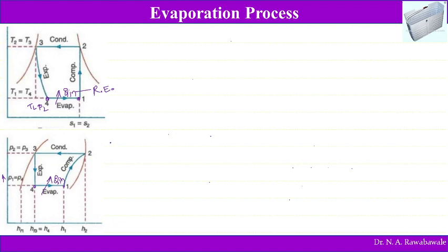This refrigerating effect is produced during process 4 to 1. During this process, the refrigerant is going to absorb heat energy, and that is given by the refrigerating effect, H1 minus H4.